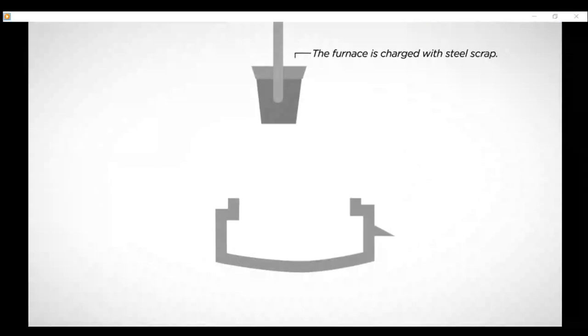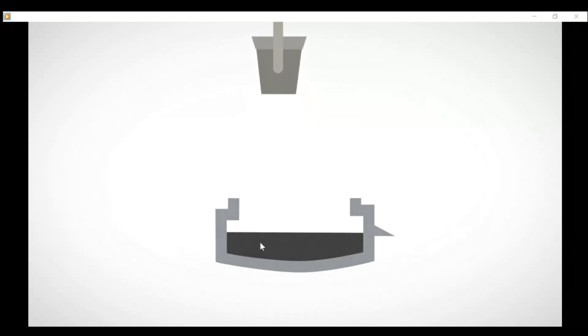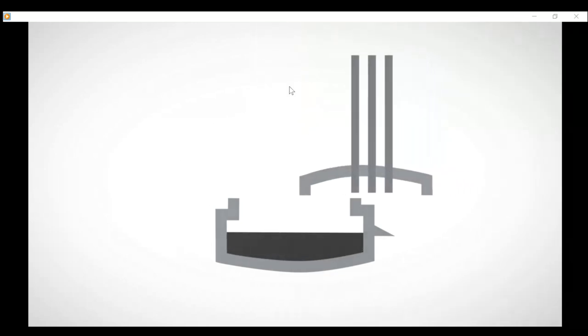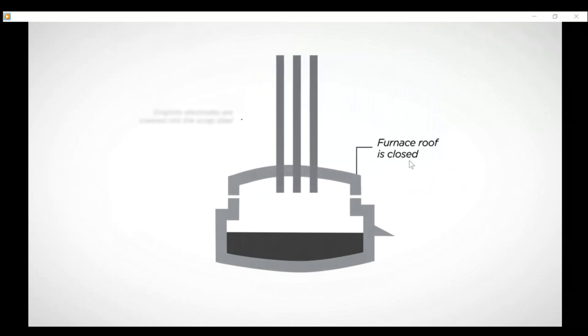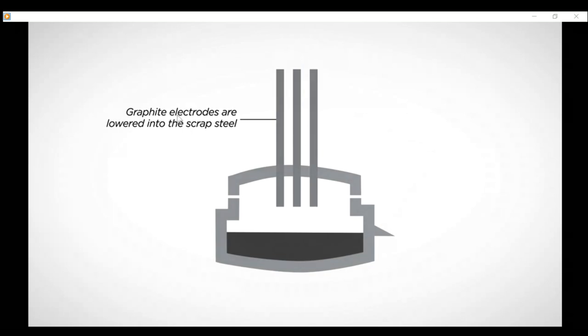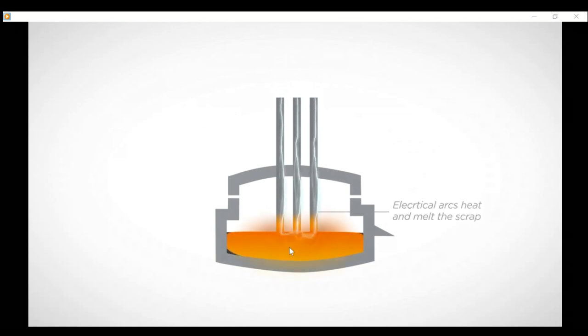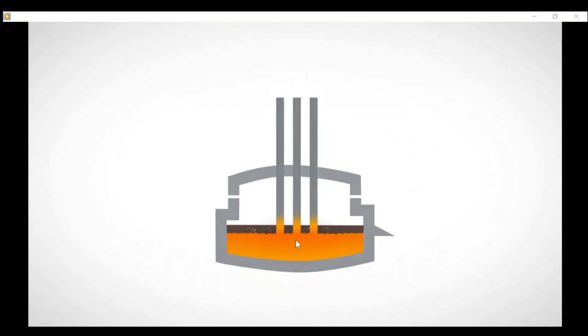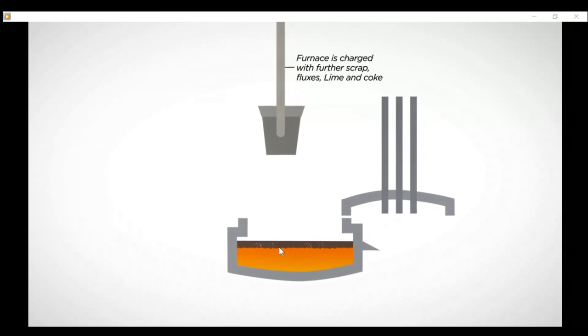Okay. This is the electrical furnace. You see that in the electrical furnace now we're charging, meaning putting in the raw material. This is the raw material and the flux, right? This is the cover. This is the electrodes. The furnace is closed now, and these are the electrodes, usually graphite electrodes to withstand the heat. This is the charging now. This is a discharging of electricity. Then when it discharges here, electrical energy becomes thermal energy, and then heating and melting. This is the top. This one is slag.